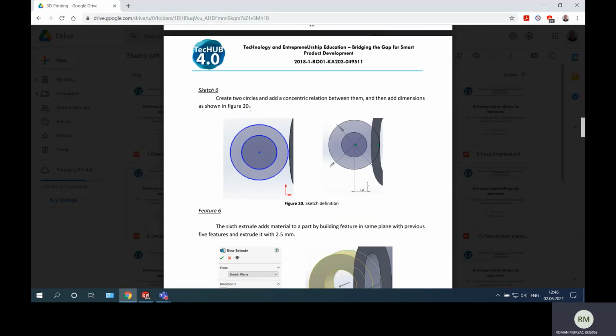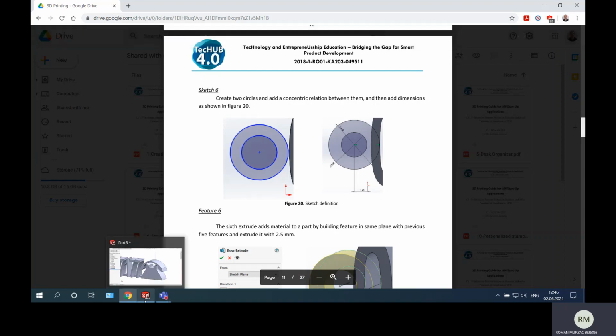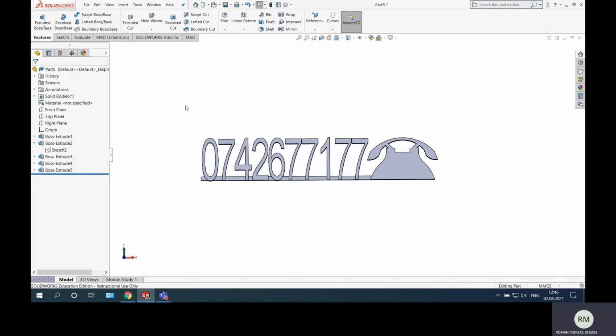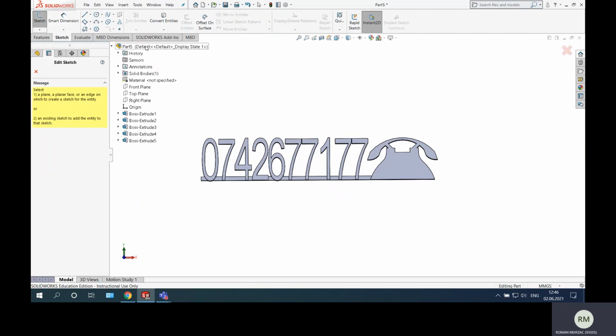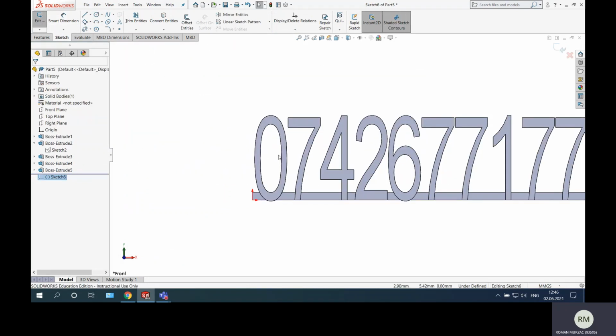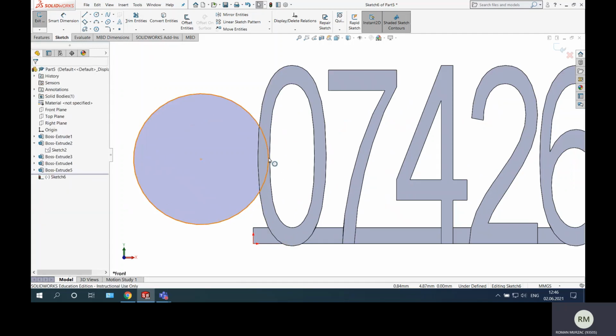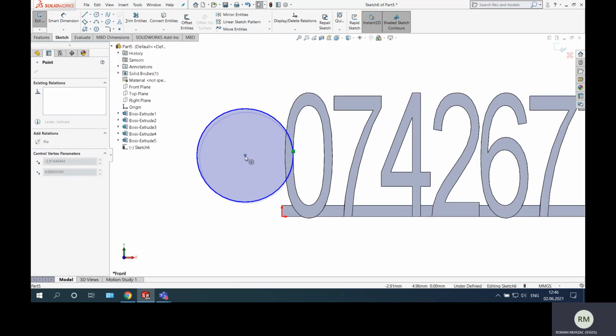Now I will make the connection ring, so it will be a connection ring here on front of this one. So create another sketch, of course again on front plane, again look perpendicular to it, and make a circle here, somewhere here, and I will do it to be coincident with this, so it's coincident, and it will be on middle, so now it stays there.